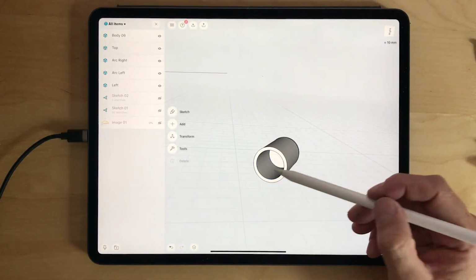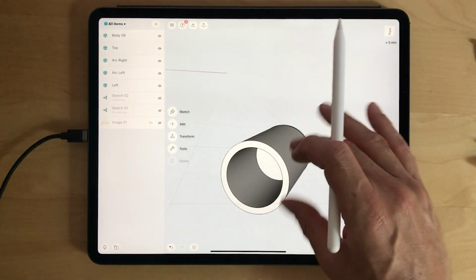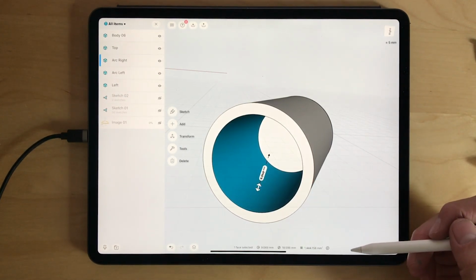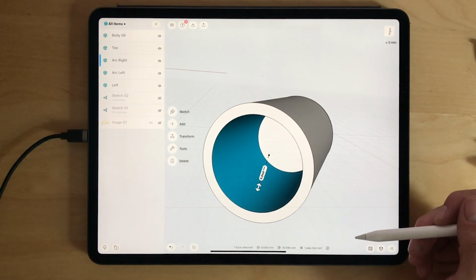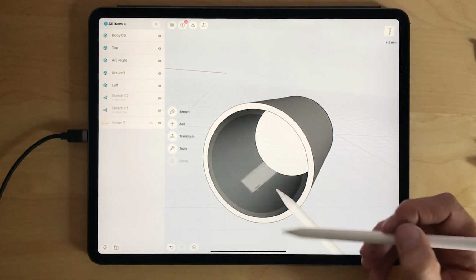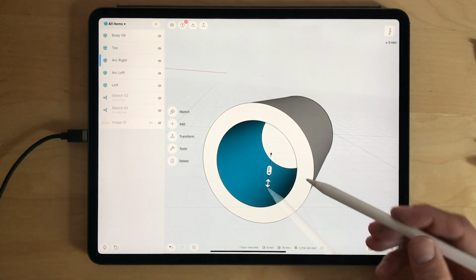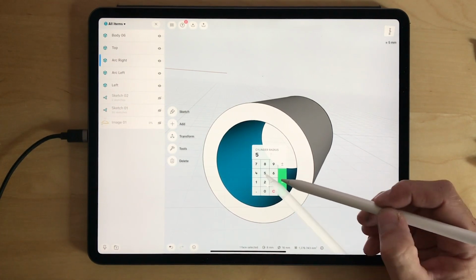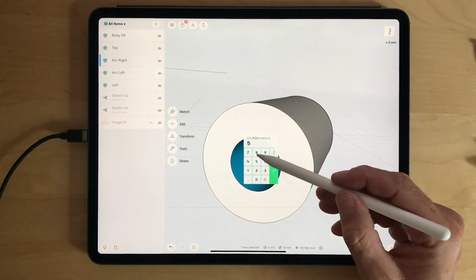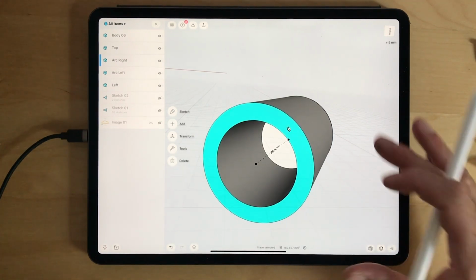So let's say through the injection molding, they think, well, the way I designed this is maybe nice visually, but it's just not strong enough. So this dimension has to be changed. Then they could use the CAD model, and like I do here right now, they actually would remove it. So in this case, I have an excessive amount of plastic, and they would say, well, if you just go to 8 millimeters, these rings would still be strong enough.